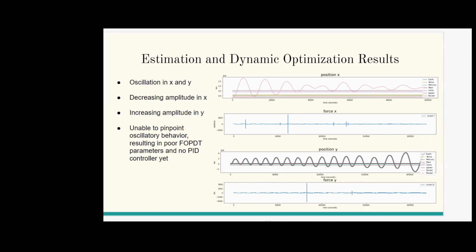We have a theory that we'll discuss in the conclusion and discussion section. But ultimately, we weren't able to optimize the FOPDT model because of this oscillatory behavior. And so a PID controller has not been implemented yet.